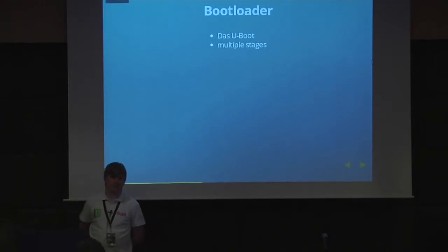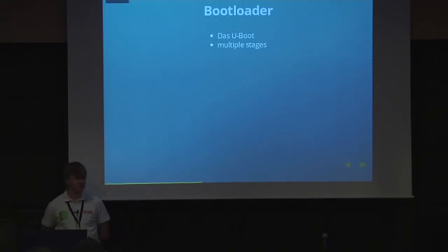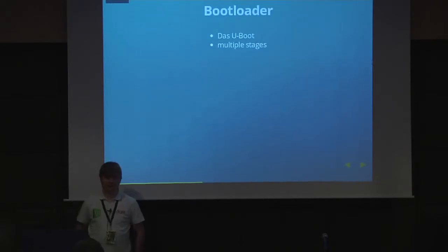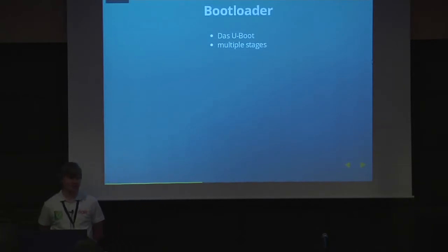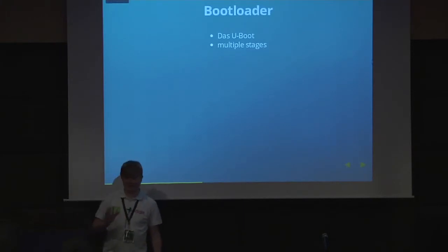In other cases, you'll see proprietary, potentially multi-stage bootloaders. In the case of the Raspberry Pi, they have a custom bootloader code just due to the unusual nature of the Raspberry Pi's architecture, where you need to boot the GPU first, as the Raspberry Pi's processor is actually intended to be a multimedia coprocessor. You need to load this binary blob of the GPU firmware just to get to the point where you can load a second stage bootloader to load the kernel to boot your Linux OS.